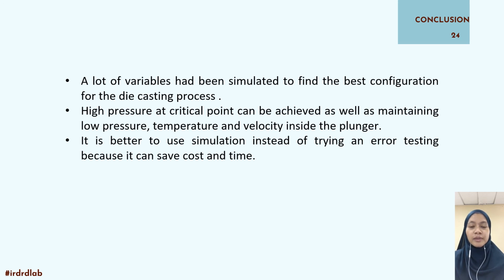To conclude, with the proposed configuration, we can attain the high pressure at the critical point as desired to disperse the air bubbles, yet we can maintain low pressure, velocity, and temperature at the plunger, which helps to increase the lifespan of the machine.